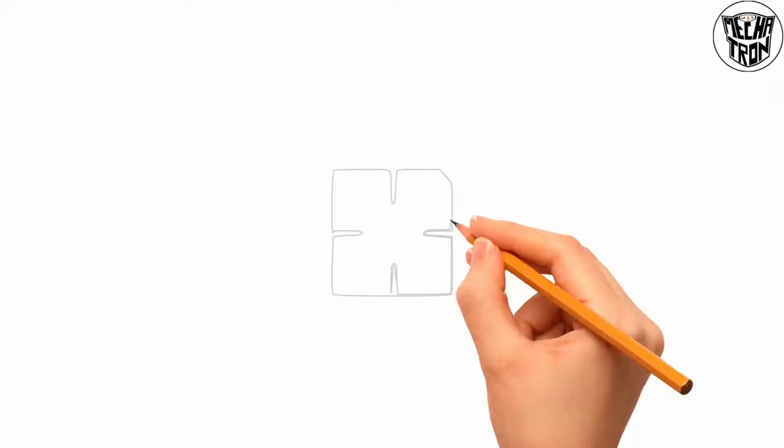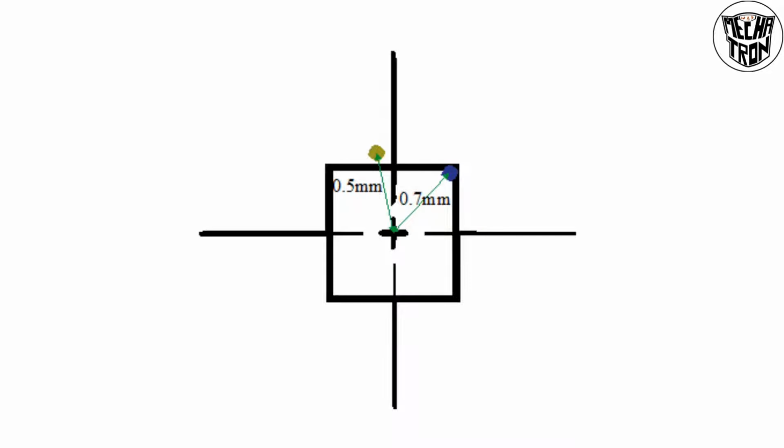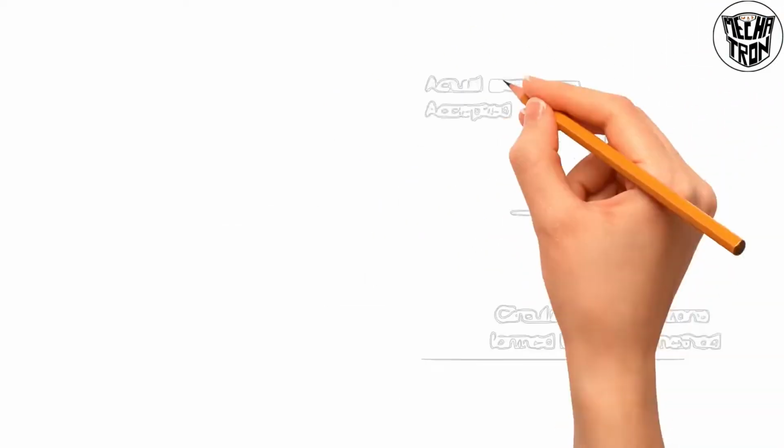At that time, they looked at the differences in the distance of this rejected nut. You can see here, this blue dot is at the longest distance of this tolerance zone, but this point is located inside the tolerance zone. And this red dot is located outside this tolerance zone, but its distance is less than this longest distance. To overcome this problem, they created the circular tolerance zone.